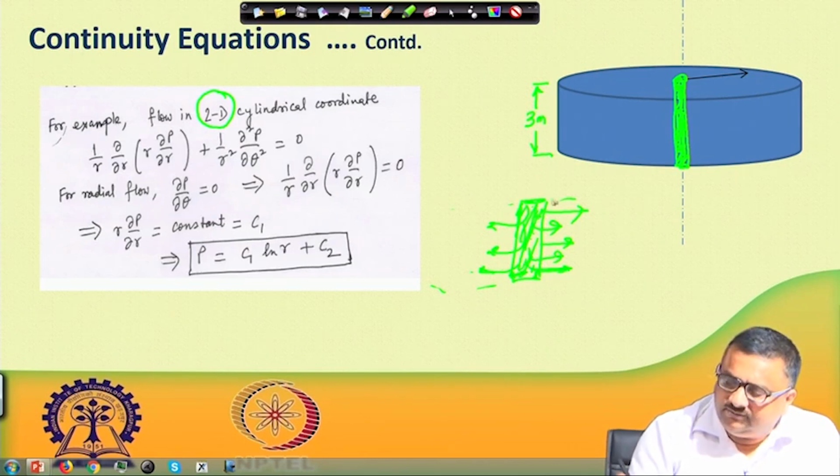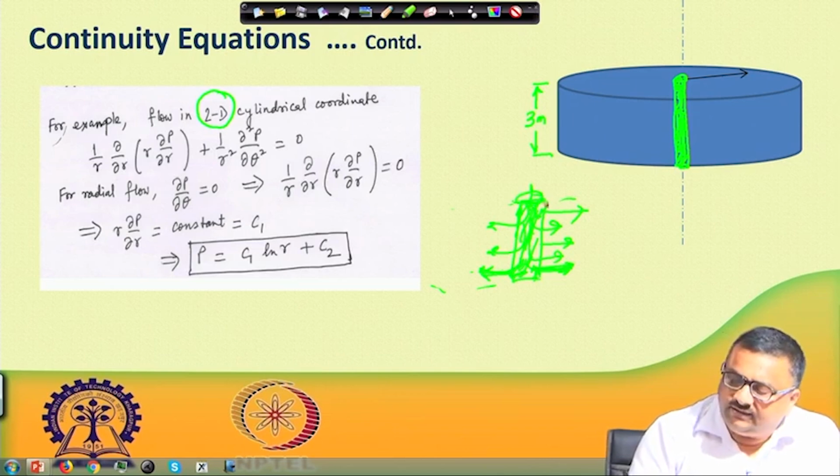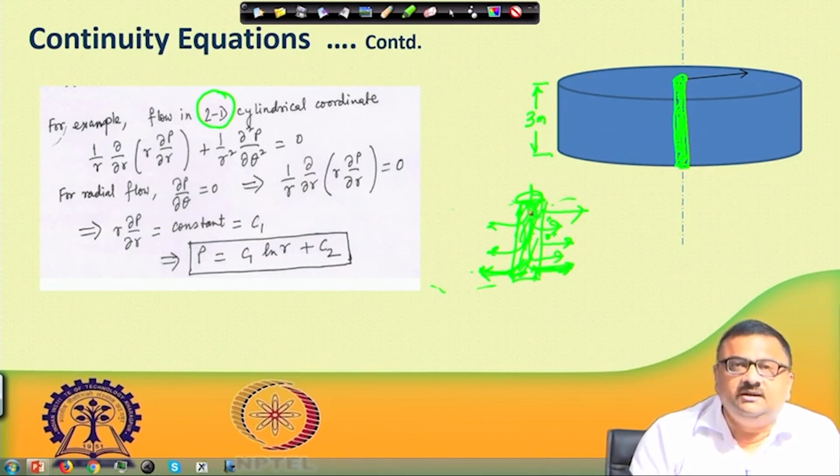So, there has to be a pressure gradient, obviously, because you can see here the flow is going in, and then some material would be entering into the porous medium here. So, there has to be some flow from the top to the bottom, and so there has to be some differential pressure. But given the fact that this diameter is much larger compared to the pore space through which the fluid is pushed in, I can say that this pressure drop is not very significant.